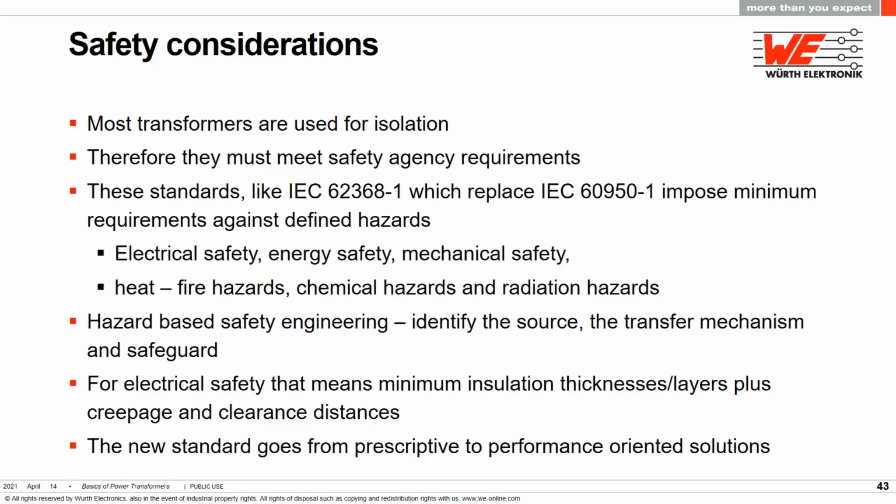One of the key differences between IEC 62368-1 over the previous standard is that they're trying to go away from being prescriptive based to being more performance based. In the old standard, they told you exactly what to do. In the new standard, it does the same, but it leaves the option open for new technologies. It allows you to demonstrate performance and to adapt new technologies without rewriting a standard.